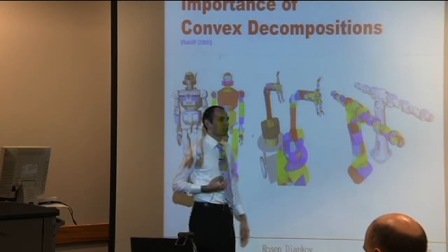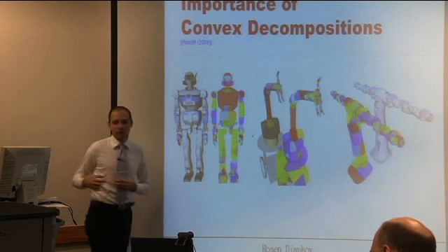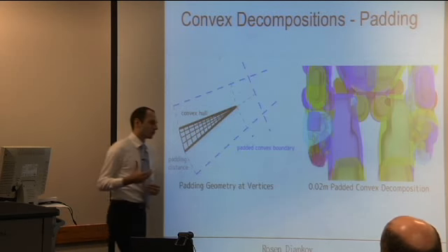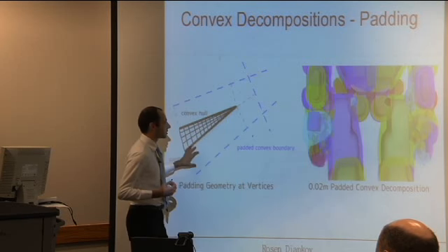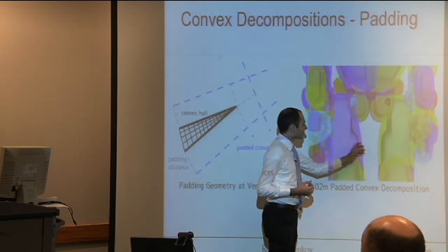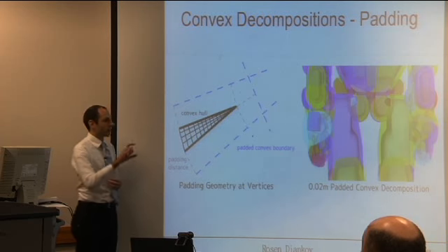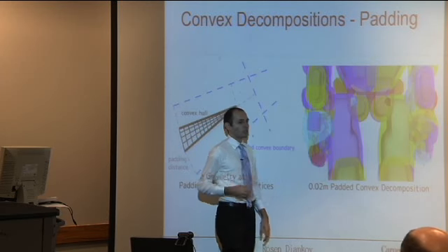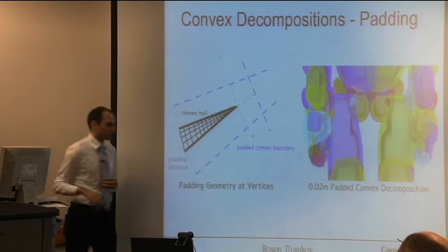But also in the thesis we discuss usages and the importance of convex decompositions in planning. And we argue that convex decompositions are really important for robust planning and for being able to do 3 particular tasks in the planning process. One of them is padding. Using convex hulls, we can pad the object much better with a particular radius of safety for the object. And these types of padded models should always be used when you're avoiding objects, but for self-collision and for approaching objects when you grasp, they should not be used.